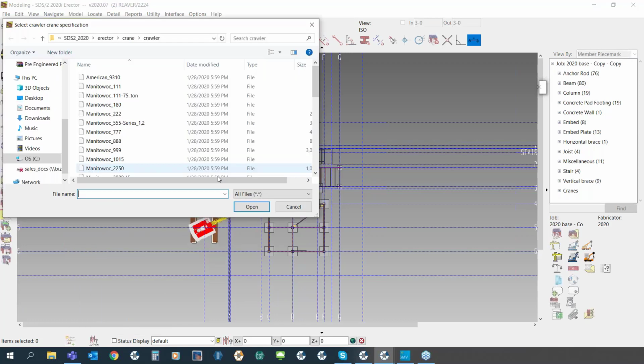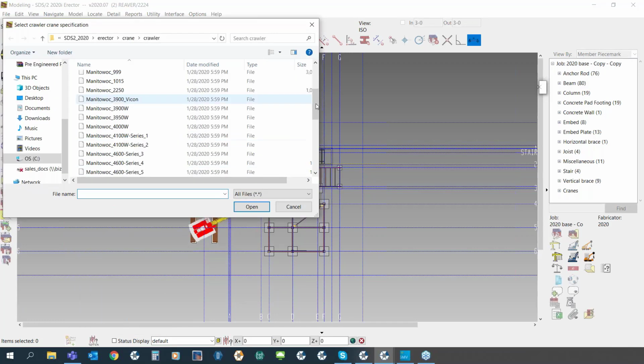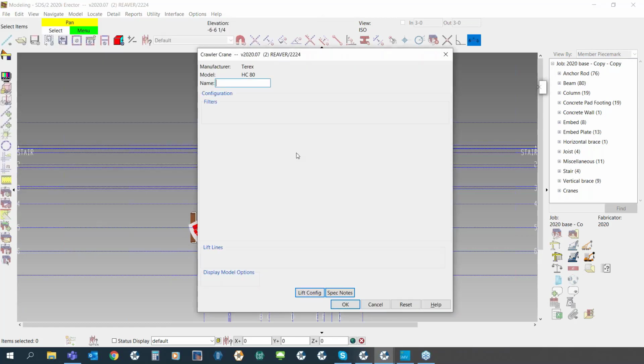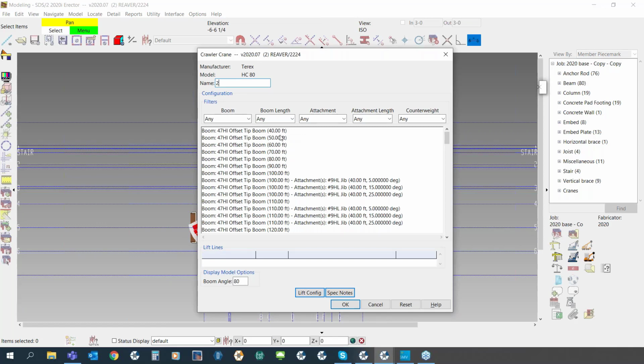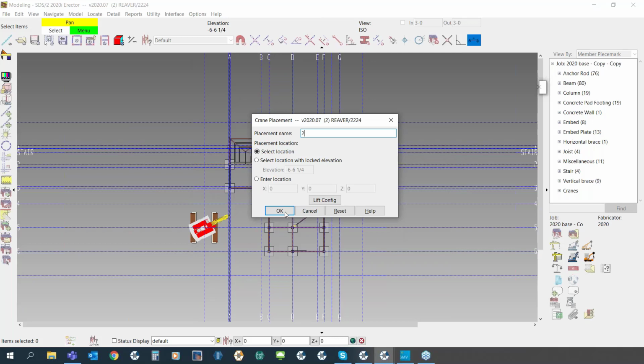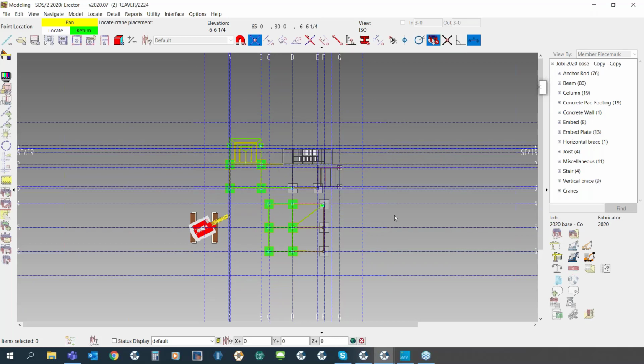And this is just our second crane placement. So we're not going to have two cranes on site. We're just going to have one crane sitting there, then we're going to move it to this point over here. And this will allow us, when steel's coming off a truck, to know where we want to place it where it's not going to be in the way. Just giving you that extra knowledge and chance to prepare up front, so you don't run into headaches out in the field. Now, when I go to add this second crane in, I can see what the first one's going to be able to handle. I can place this one right here, and we're going to be able to get everything on this job.